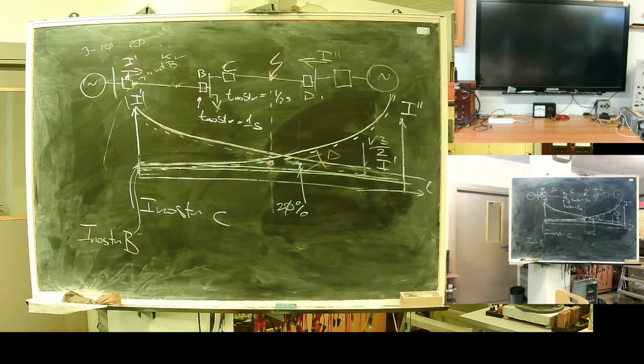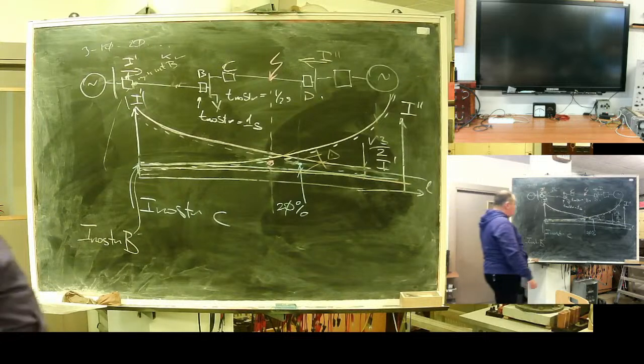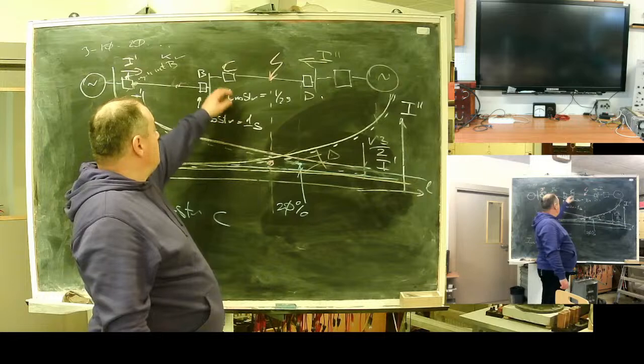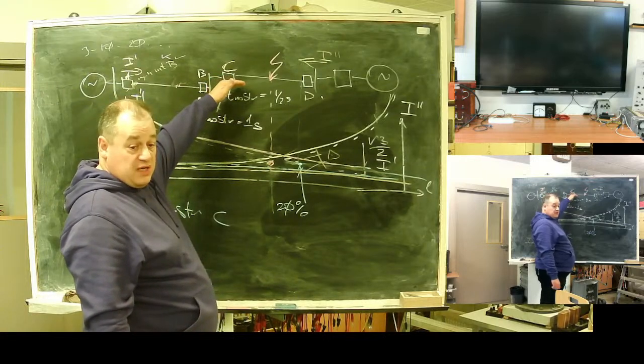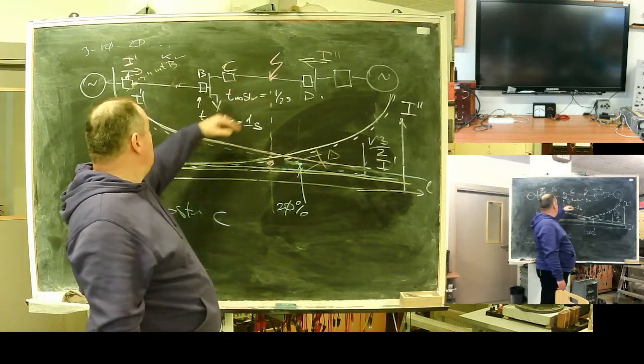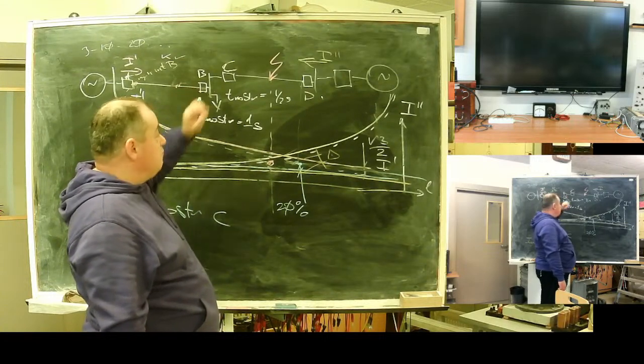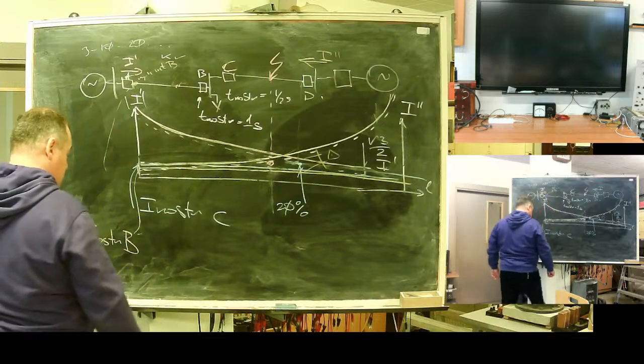Selective. At first look, what will happen? Both will start, yeah? But this one will operate in 1/2 second, will clear fault, and B will return. Fine? Fine.